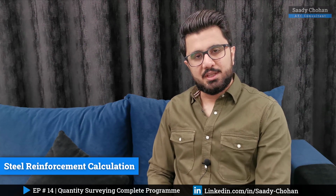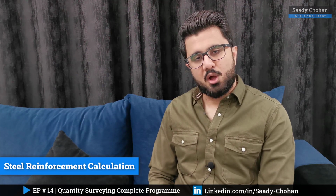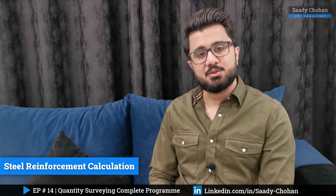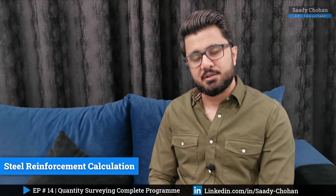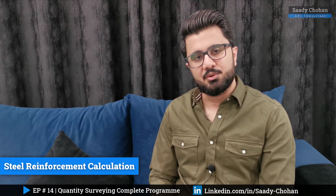It's episode number 14 and today we're going to talk about steel reinforcement, rebar calculation for our villa project. We will calculate the quantities for the footing, column, beam, slab and staircase etc. by considering different steel dia, rebar weight, center to center spacing, concrete cover, weight and quantities in kg and in tons etc. And at the end we will fill this quantity in the BOQ which is prepared by NRM2 work section BOQ. I will try my best to explain in detail.